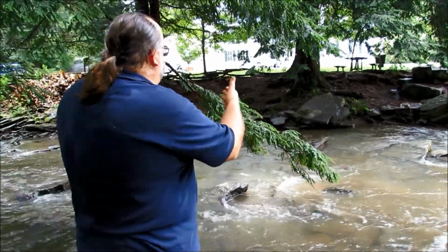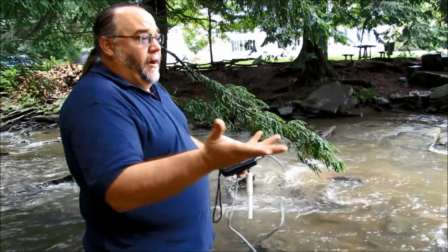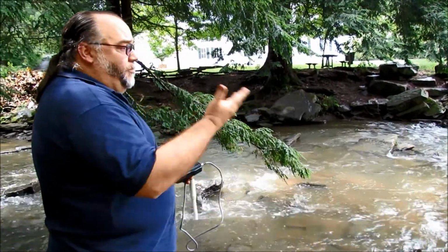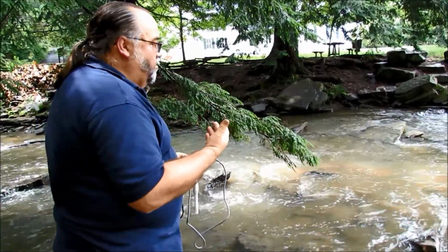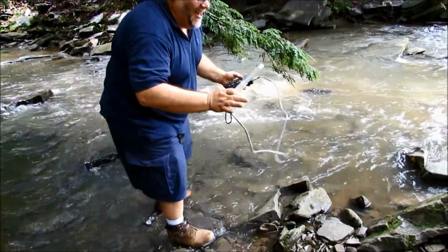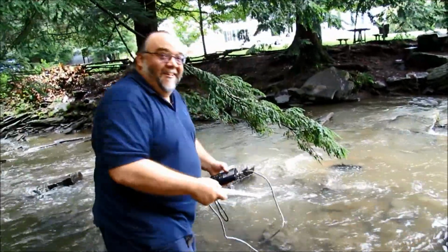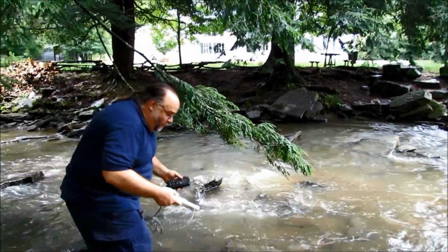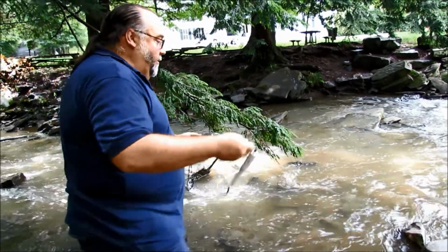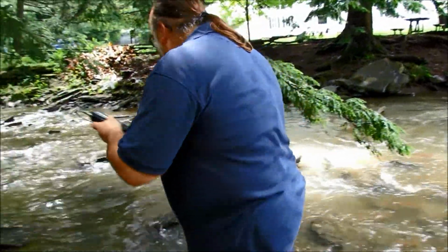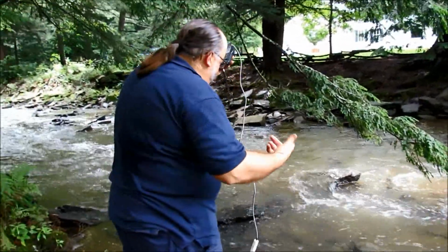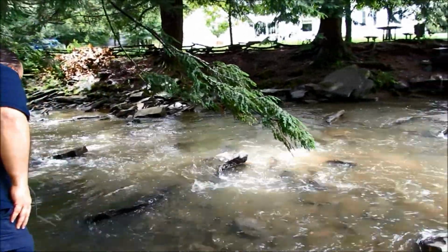Usually it is better to wade into the stream to collect, but we're not really prepared for that. I know I'm not. And it's usually not as high, obviously. So you want to come back to the same place to do your sampling. And one of the things you don't want to do are things like this, right? You don't want to do that, okay? And why don't you? What would you say? Well, you don't want to measure water quality while you're upstream disturbing things. So typically you try to get to a place where you can be off to the side, which is one of the reasons why these kind of meters are nice, is that I can actually take it and put it in upstream.